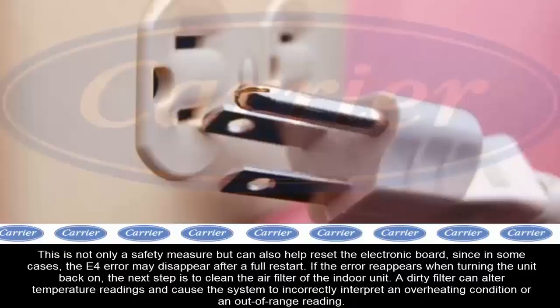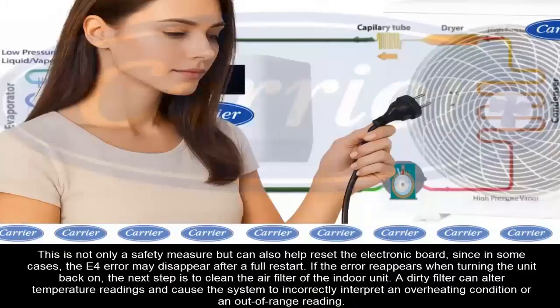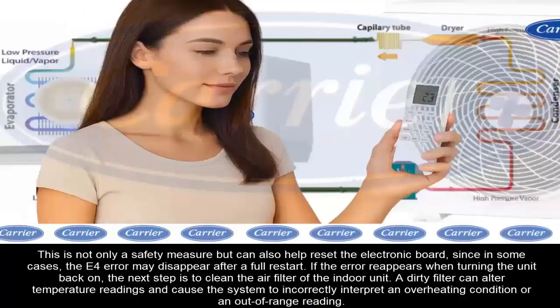Before performing any measurement or test on the sensors and before opening the unit, it is recommended to completely disconnect it from the power supply for several minutes. This is not only a safety measure, but it can also help to reset the electronic board, as in some cases, the E4 error may disappear after a full reset.